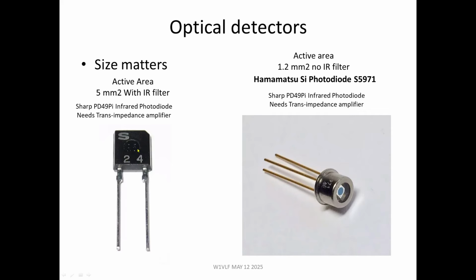This is actually the back side of it. You wouldn't use that side. You'd use the other side, which is flat. But inside here, about 4 millimeters by 4 millimeters is the active area. The rest of this stuff is just for convenience, because these were through-hole parts. I don't know how they were placed, but anyhow, you need an amplifier after this. So that's where this TIA or transimpedance amplifier comes in.